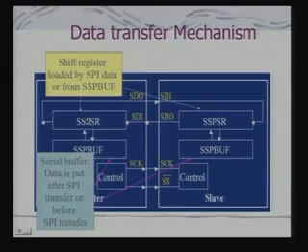Now, the data is put here after an SPI transfer or before an SPI transfer. What is interesting to note is that once the data is loaded onto the shift register, with the loading guided by the clock, it is transferred to SSP buff. So, it is a kind of serial in, parallel out operation.